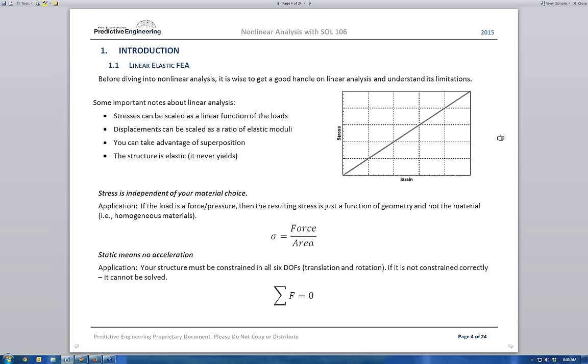So this is a little bit of background. This is a good thing to keep in mind when you're running linear analysis and you see things that might be a red flag. I also wanted to mention this because before you ever do any sort of nonlinear analysis with your model, you should always run it linear first. Start simple, and add these complexities to your model one step at a time. If you try to tackle a massive model with bolt preload and plasticity and buckling all at once, something's going to crash. And rather than hunting through all of these wonderfully complex things you've added to figure out which one was the problem, if you add them incrementally, it's a lot easier to find the red flag.